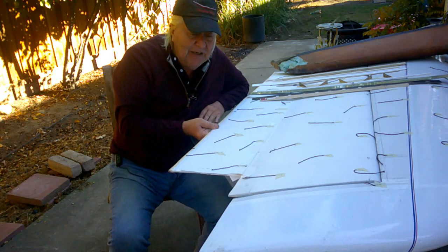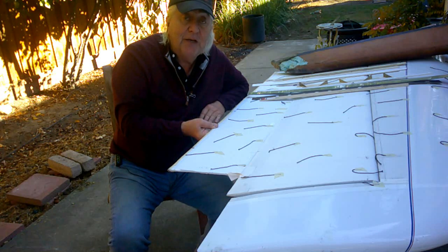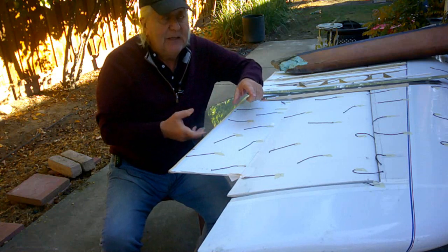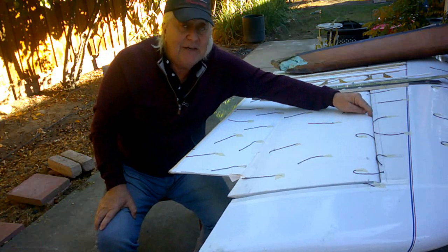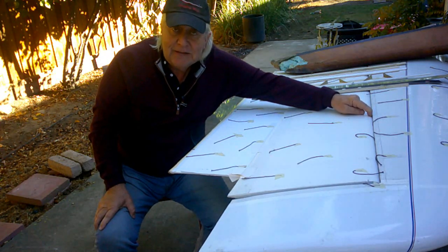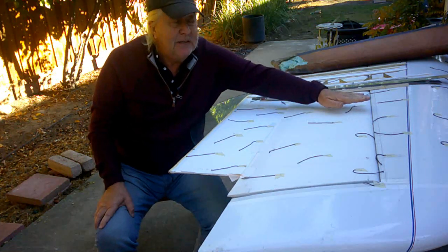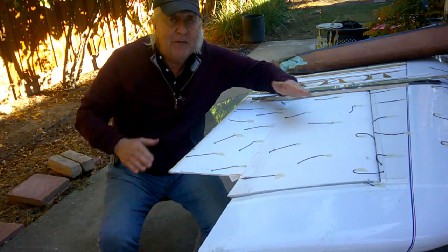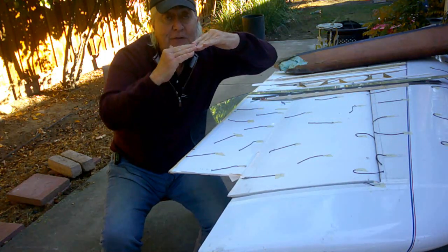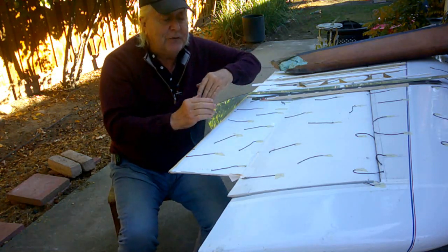So the Millennium's got the standard answer that anybody would be driven to. You want it to be transportable, so just tack an elevon on the trailing edge. Because if you've got a fabric wing and ribs that fold up, how are you going to have a hinge line like this? Mechanically, a nightmare, and probably pretty damn heavy. A more aerodynamically efficient configuration is to actually bend the airfoil, change the camber line, and efficiently generate more lift so you can roll.